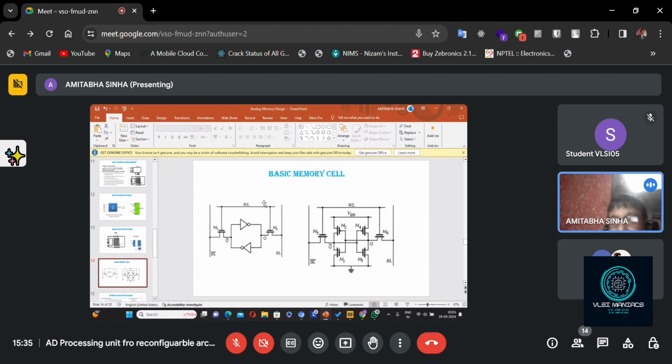Forget about all other transistors and concentrate only on these two NOT gates. Say somehow the input of the upper NOT gate is 1. So the output will be 0. That 0 comes to the input of the second one, and that will be 1. So 1 will be latched. Continuously it just says 1, 0, 0, 1. So 1 will be permanently stored.